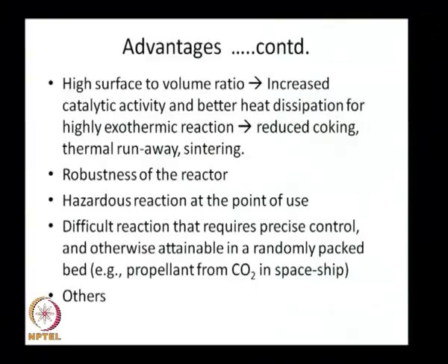Accordingly, the conversion would be guided by the amount of catalyst it encounters. If too much catalyst is there, extraneous reactions could set in, and there could be thermal runaway, that means a lot of heat gets generated, and if it cannot be dissipated quickly, there would be sintering, and the catalyst gets destroyed. Also, if unwanted products are generated, that will result in poisoning of the catalyst.